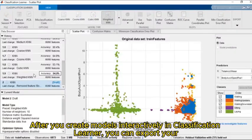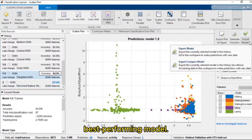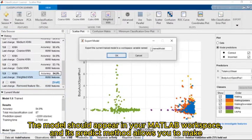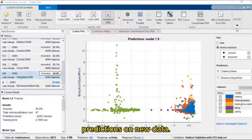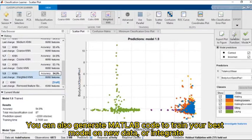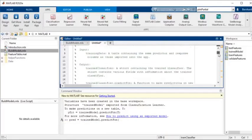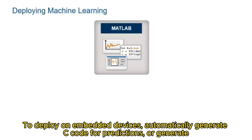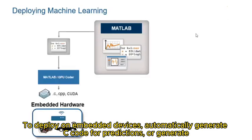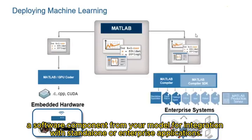After you create models interactively in Classification Learner, you can export your best performing model. Click Export. The model should appear in your Matlab workspace, and its predict method allows you to make predictions on new data. You can also generate Matlab code to train your best model on new data or integrate trained models into computer vision, signal processing, or data analytics. To deploy on embedded devices, automatically generate C code for predictions or generate a software component from your model for integration with standalone or enterprise applications.